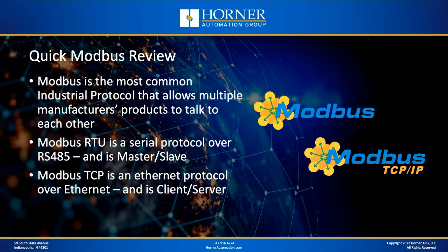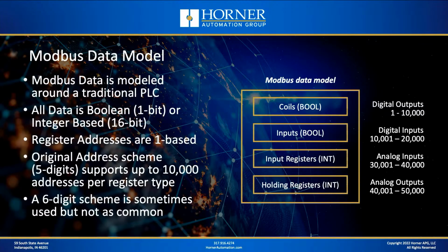a client-server protocol. Now remember, Modbus has been around since the 70s, and because of that, it's modeled around a traditional PLC. And a traditional PLC of those days consisted of 2 different types of data: Boolean data, which is 1-bit based, and integer-based data, which is 16 bits.